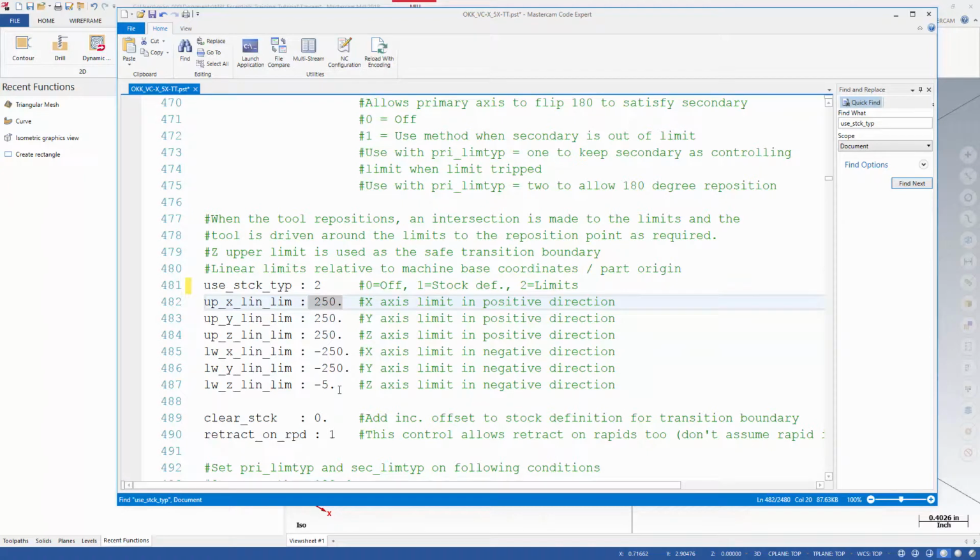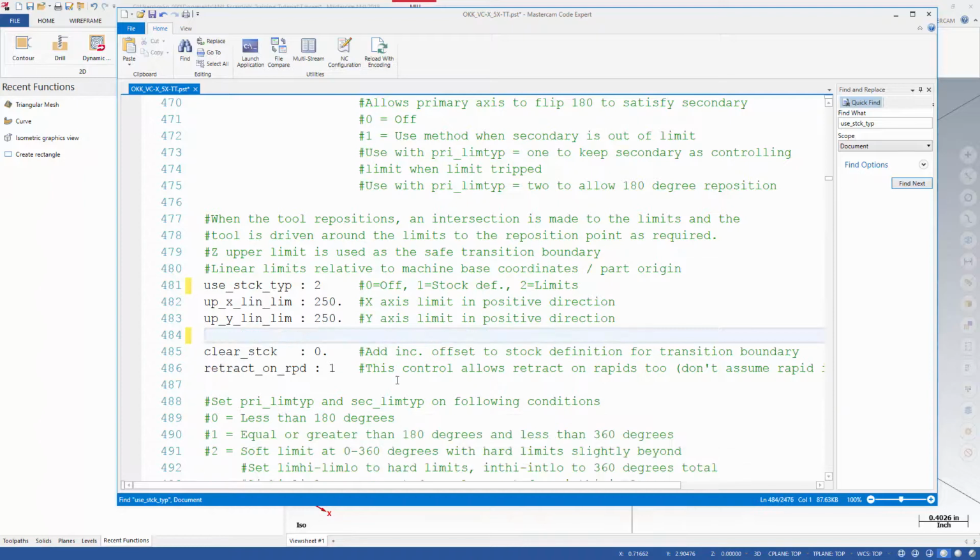Especially if the Z value that you're outputting is the pivot point of the gantry. Because this might be something like, in inches, maybe the lowest this can go is like 31.254 for the lower limit. That's low. And then upper might be something like that. So you have to measure all those numbers and put them in.